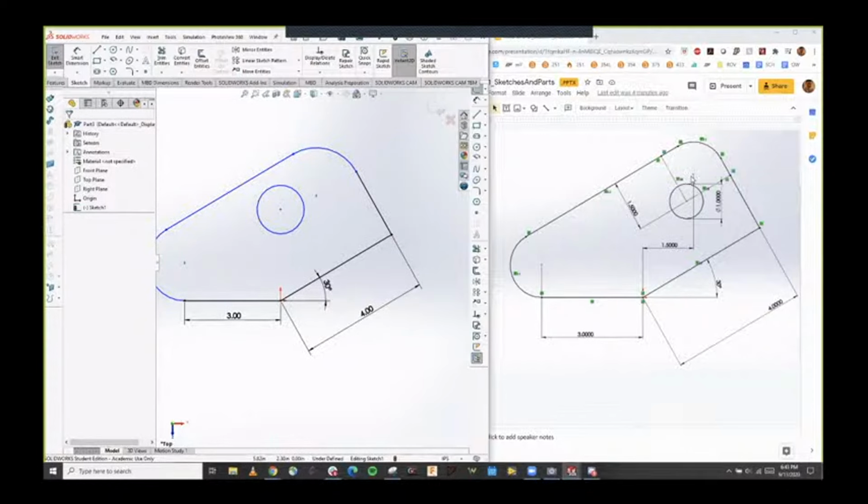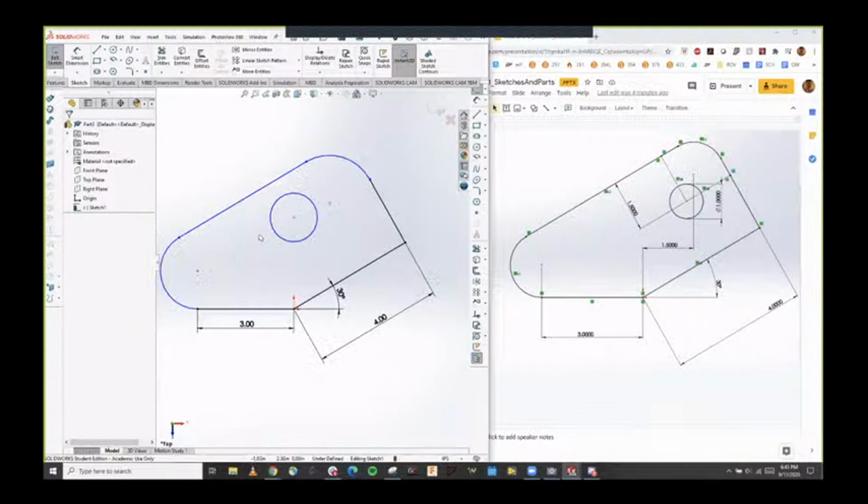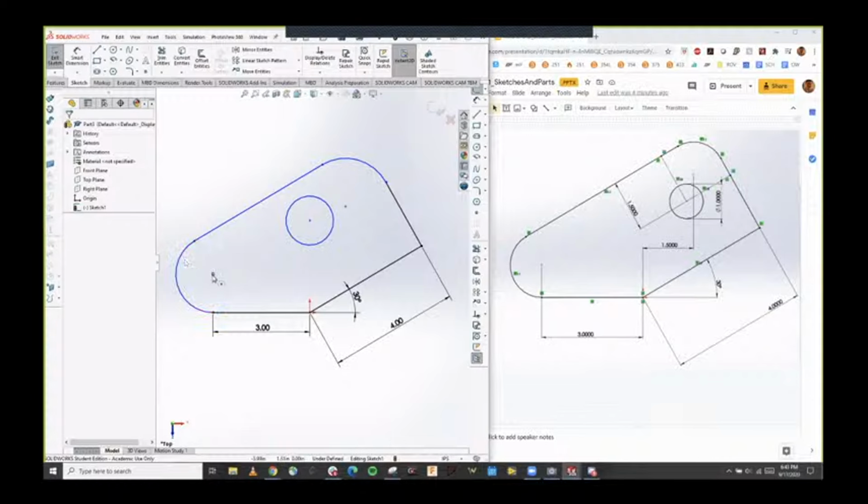As we see in this picture up here, there are 2 crosses. Every arc and circle has a cross to denote its center so that you can put constraints between the center of a hole and the edge. So you can't really very easily define the distance between an edge of a hole and the edge, but the center is always constant. So if we need to, we can do math to make sure that this distance is enough. But we always define holes and arcs by their center point, not their distance from the edge.